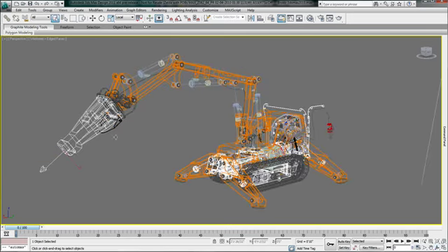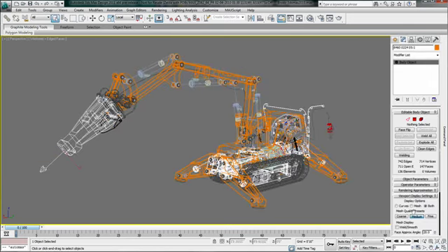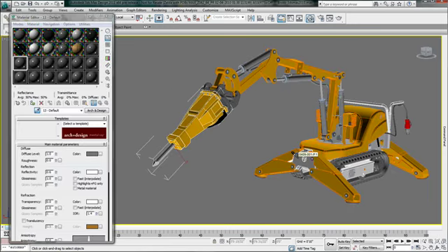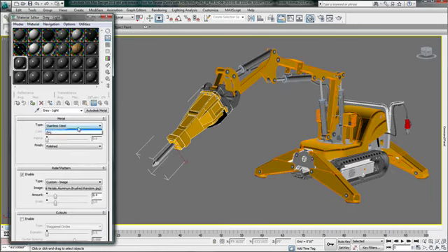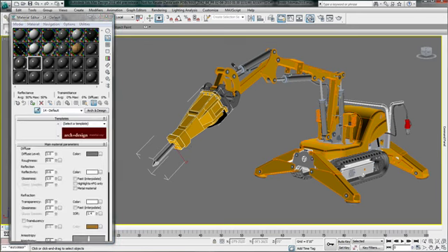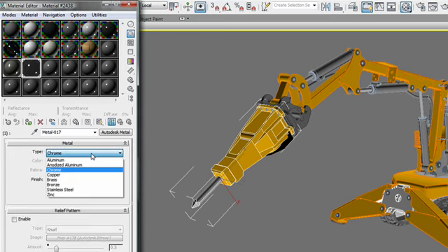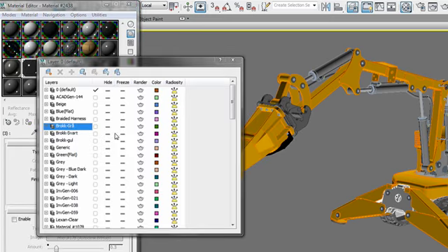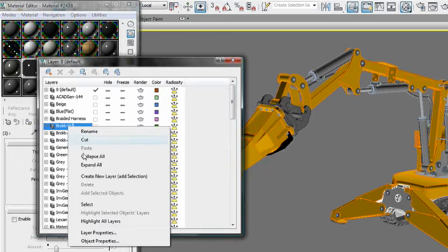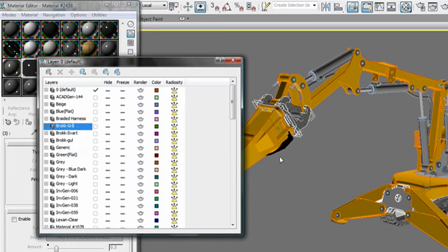While in wireframe mode, I can clearly see the body objects keeping the curve data information from Inventor in its native form. By opening my material editor, I can start loading a few of these scene materials. You can see that the Inventor materials are kept, in this case, using the Autodesk Common Material Library. If I look at my Layer Manager window, you will see that the layers have been named and organized according to the Inventor materials, helping with scene management.